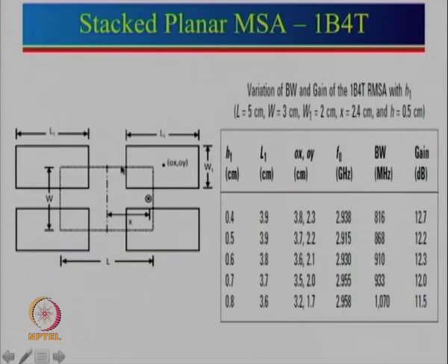Again the feed point is very close to 24 centimeter. For the top patches, all are identical, but we have taken a much smaller W for them, and I will tell you the reason. The top patch is being fed along the diagonal. So, if this width is comparable to this length here, then what will happen? Orthogonal modes will start getting excited.